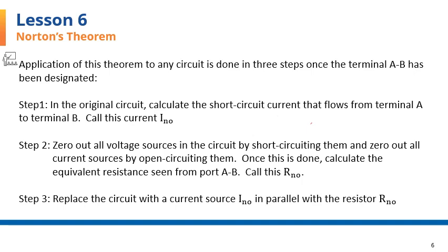I should mention that to zero out a voltage source, we replace it with a short circuit, and to zero out a current source, we'll remove that source, leaving an open circuit in its place.